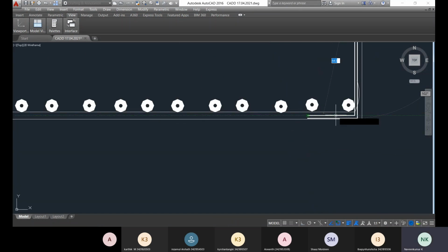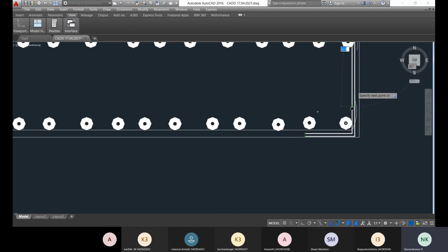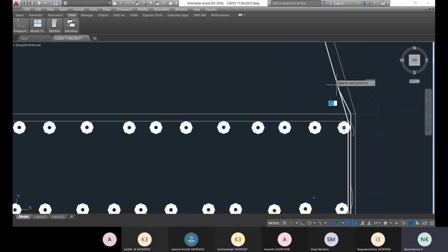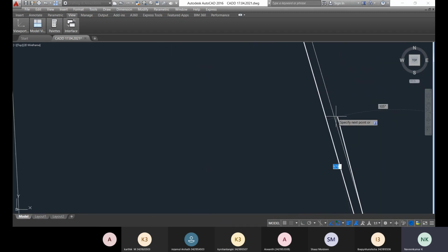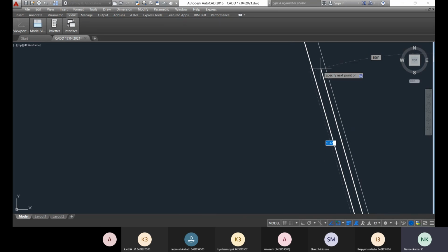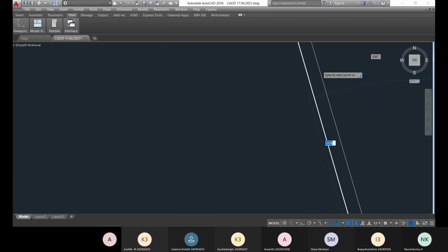Okay, so the secondary curtailment bar starts from here and it covers the thickness of the base slab. After that, it is going to travel and be provided in the stem. Up to which distance you can provide it, we have seen in the design: up to the distance of root of h. The overall height of our counterfort retaining wall is 7.8, so root of 7.8 will give you the curtailment bar distance.